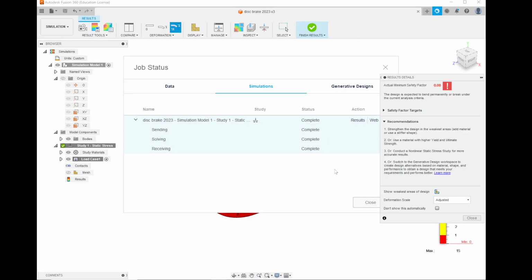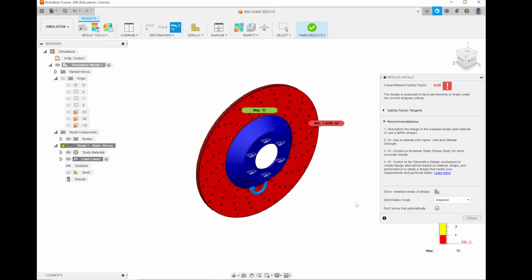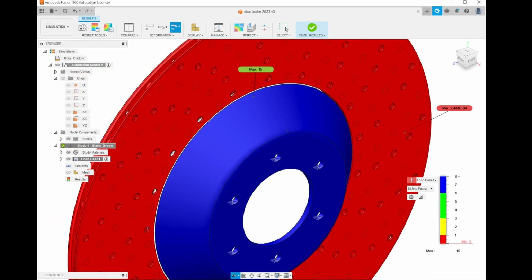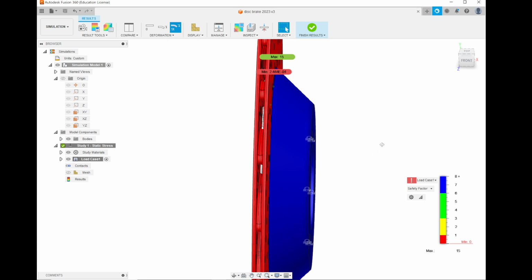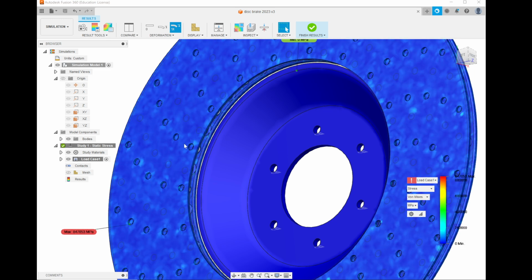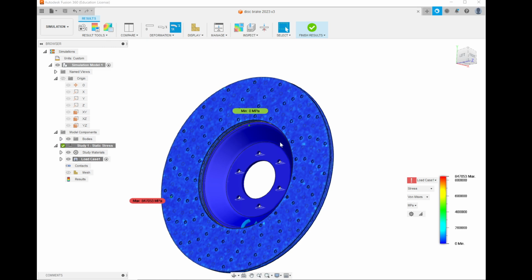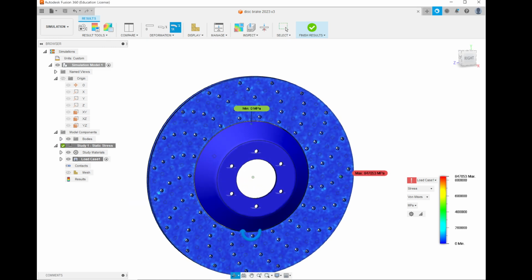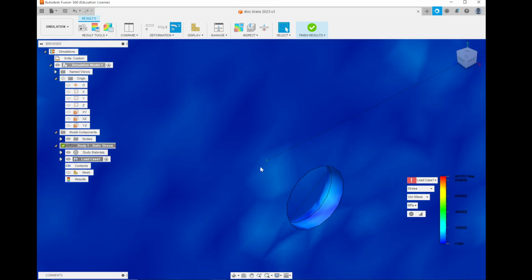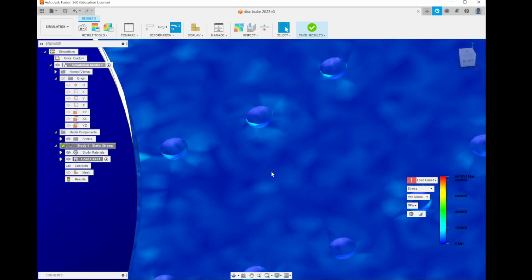So this thing has fully received everything, so I can press OK. Did this work? I don't know. So I put a moment on here, and let's see what's happening. Factor of safety, I don't actually want factor of safety. I want stress. That's enough. So I have stress over here. If we look at the place that has the maximum stress as I put a torque, it should be this component over here. Is that like an interior component maybe?